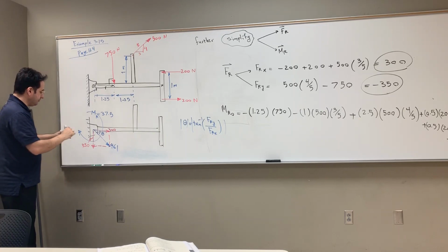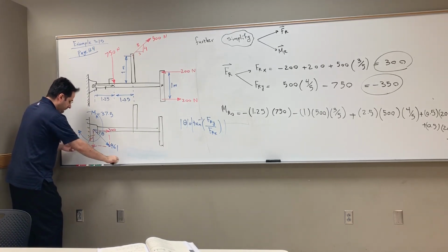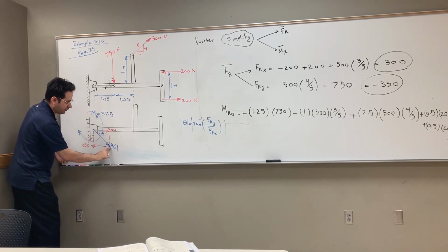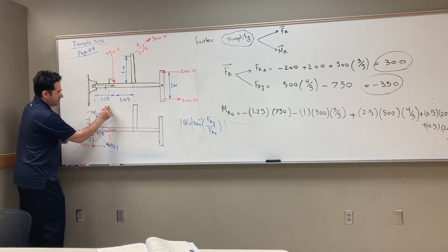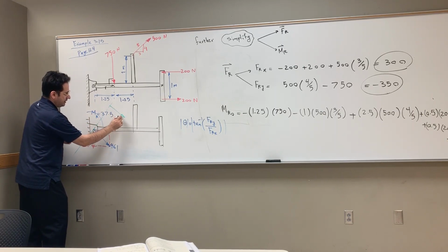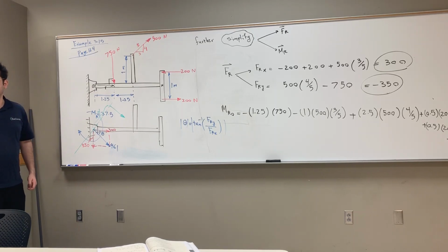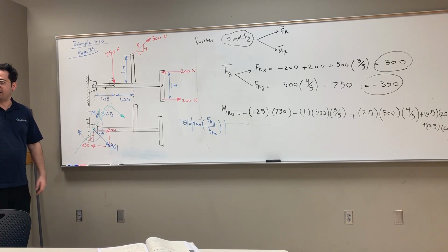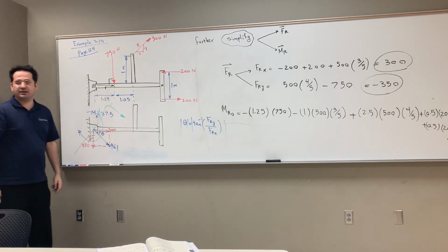So let's do that. At what distance should I move this 461 Newton force sideways? Means that along this line, for example here. At what distance d should I move that such that I get the same amount of moment that I already have here? So I can just delete this moment and just have the single force acting at that particular distance. So what is that distance? Is there anyone that can solve it?